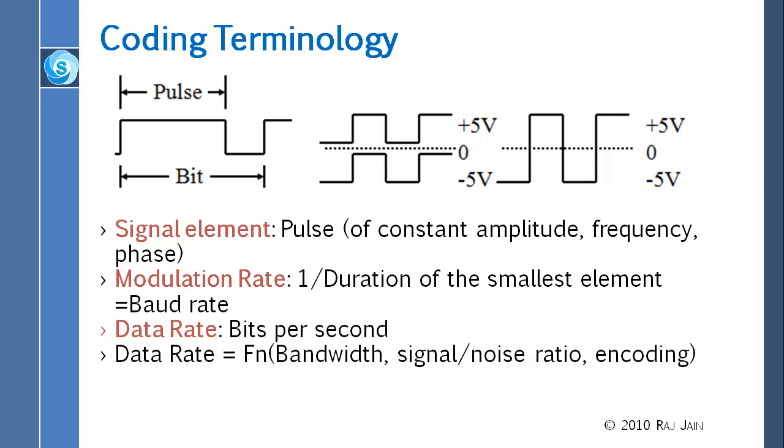So for example, this signal, if I told you that each of these horizontal parts is 1 second, what is the hertz rate of the signal? Half cycle per second. Why? Because this is 1 second and this is 1 second, the whole cycle, you have to take the whole cycle. You start from 0 and then when you come back to 0, it takes 2 seconds. Each cycle is 2 seconds, right? So this is half cycle per second.